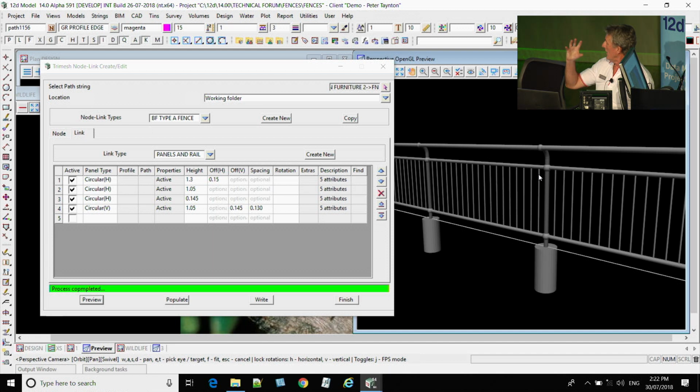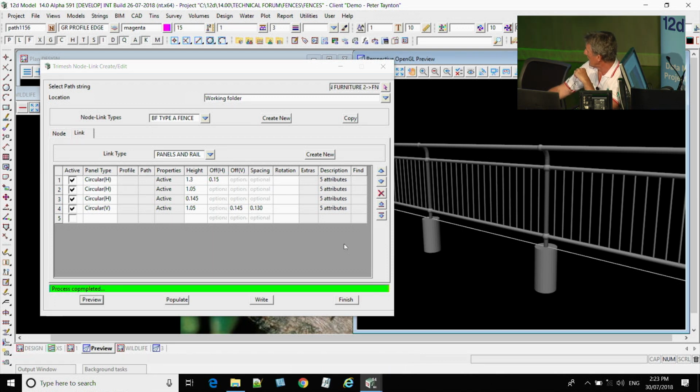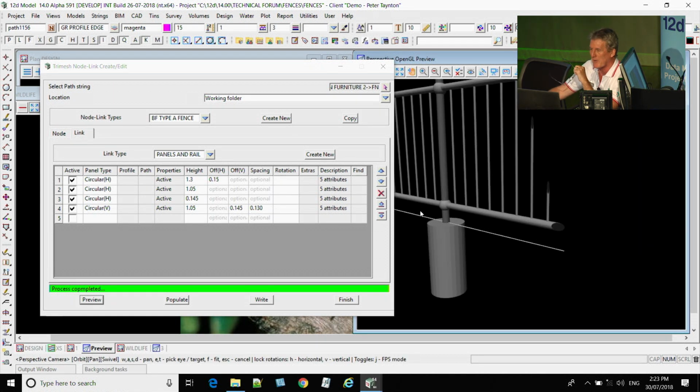Now Paul did a sphere for it, and I said, who the hell's ever going to use a sphere in 12D? Other than trying to explain the geoid thing of 2020. But it actually did come in useful pretty well straight away. The next day, I think I had to do that fence. So it was pretty handy for that. And we also used it for the traffic lights that we'll show you in a moment, where we needed to do the light of the traffic light, which is a sphere globe, pushed downwards. So we had to muck around with that, and then we cut that in half and then translated, factored it, and got it to look like a light. So there's two things I use the spheres for.